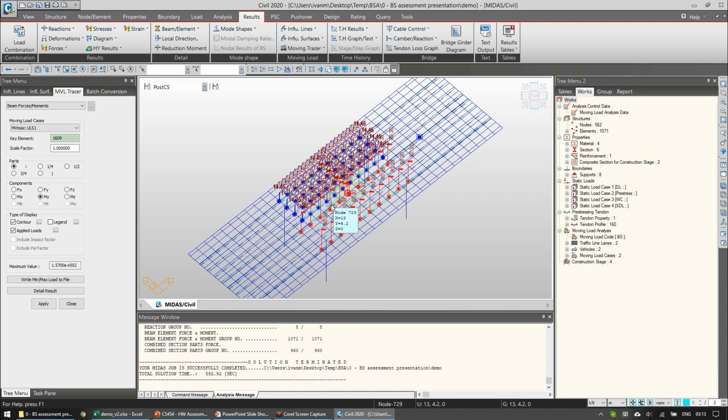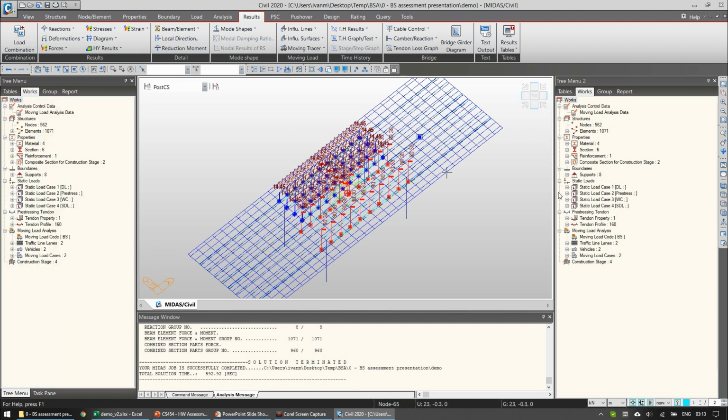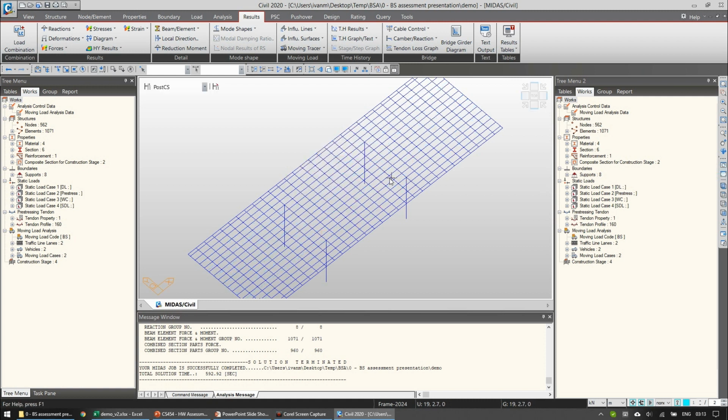This is the one still driving how the two vehicles should be applied, with the exclusion zones in front and after the vehicle, and when straddling, pushing from one lane into the other, and so on. But this is as per the standard moving load behavior and analysis in Midas, so we're all familiar with that, and you can find plenty of information if necessary.